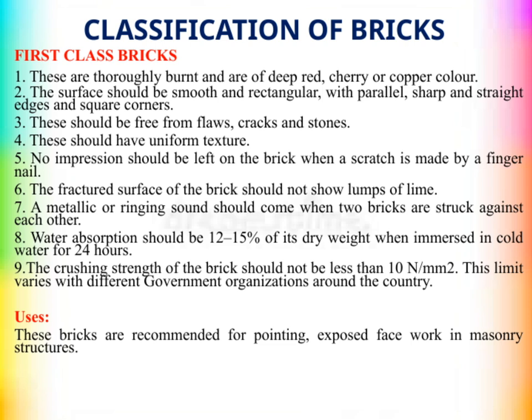When you strike two bricks together, they should produce a metallic or ringing sound, indicating good soundness and strength. Water absorption is also a critical factor. For first-class bricks, this should be between 12 and 15% of their dry weight after immersing in cold water for 24 hours.